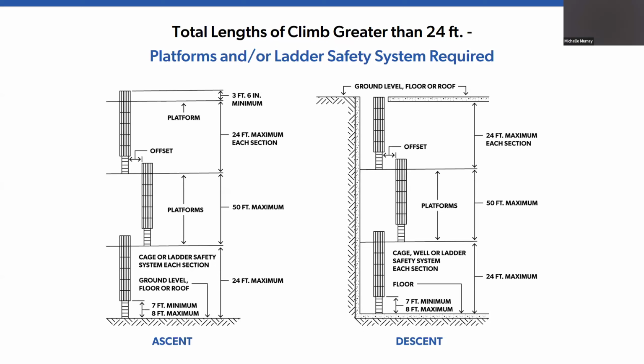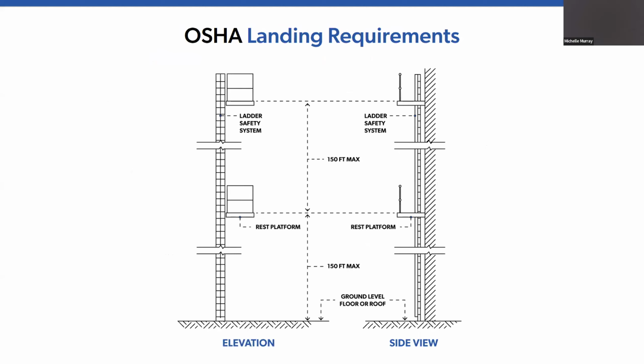If the climb is greater than 24 feet, a platform and a ladder safety system will be required. The OSHA landing requirements you can see on this figure here.